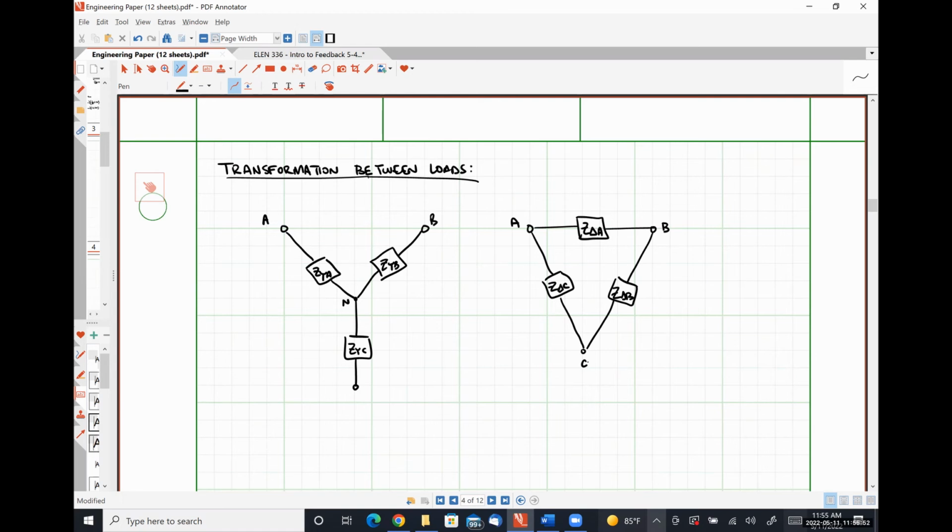What we are about to do is to figure out the rules that will allow us to replace a Y connected load with an electrically equivalent delta connected load and vice versa for an unbalanced case. And then we are going to see what falls out when we constrain these systems to be balanced. Okay.